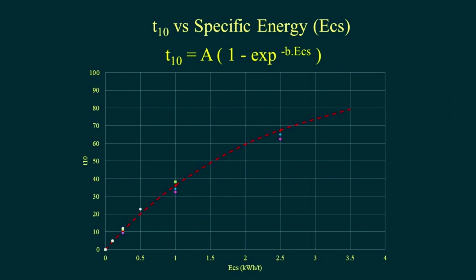Let's look at, for example, the AG and SAG mill model. And if you remember, this should be familiar to you from when I looked at the raw JK drop weight test data. The drop weight test is known mostly for being used if you wanted to do AG and SAG mill simulations. And you get out of that drop weight test that line there, which gives you an A and it gives you a B. And inside the AG and SAG mill model, there's an algorithm which calculates for each particle size how much energy is actually used to break it.